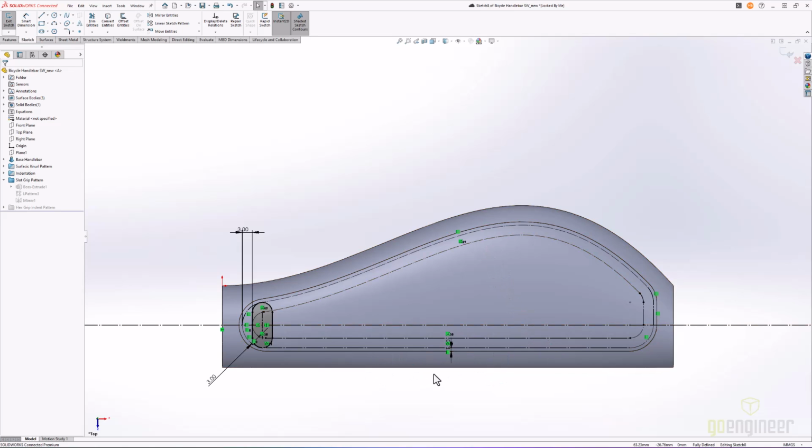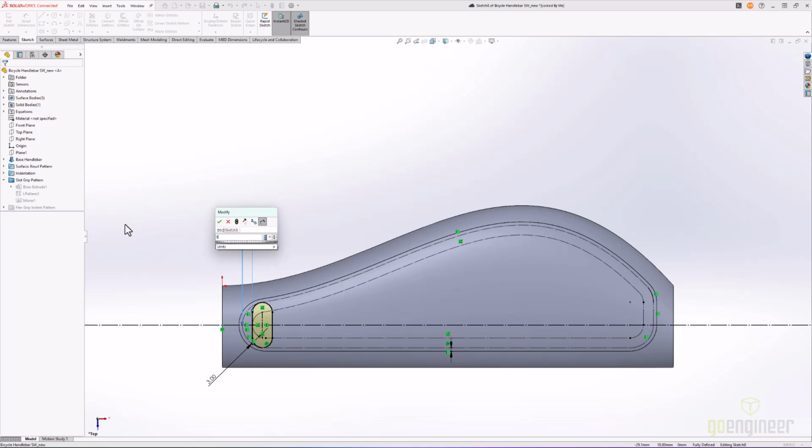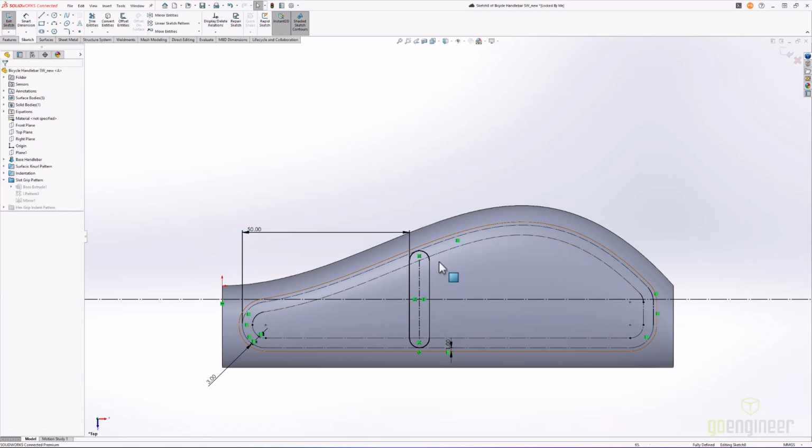The rest of the constraints which determine the geometry of this profile are geometrically constrained rather than dimensionally constrained. This means, as one might expect, if I increase the offset here, and the bounds of this slot are designed to follow this construction geometry, that when I confirm that, we can see that the slot geometry changes.